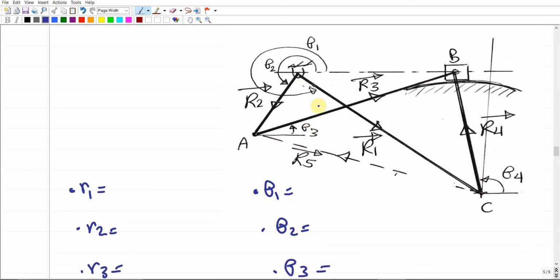So it means that I can skip the calculation of R1 for the moment, but generally speaking, for any position vector that is set up between two fixed points in the mechanism, these two points are all the time going to be fixed during the movement of the mechanism. Definitely the locations of these two points should be provided to us or should be given. And in this case, the R and the theta of this vector that is set up between two points should be constants and they should be given. So anyway, since R1 had been set up between two fixed points, R1 will be given with a value, and we can calculate this value, the same thing as theta 1, and both are constants.